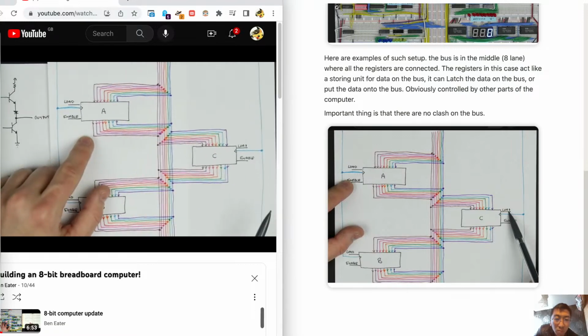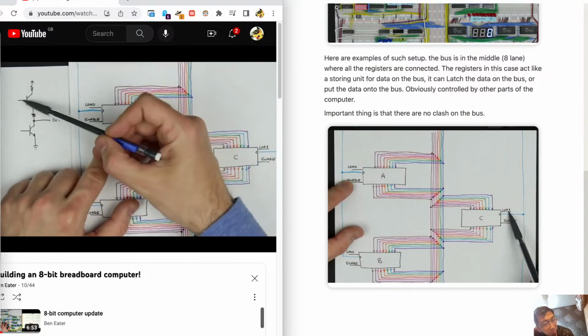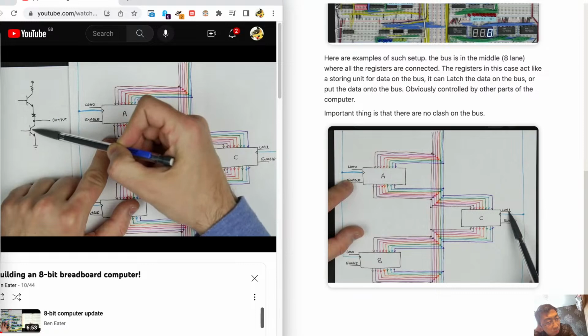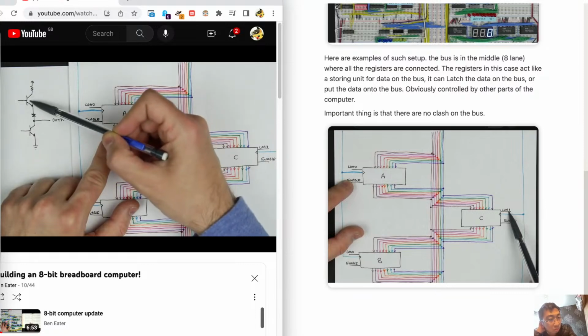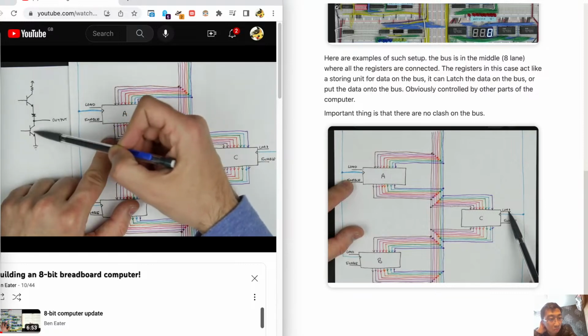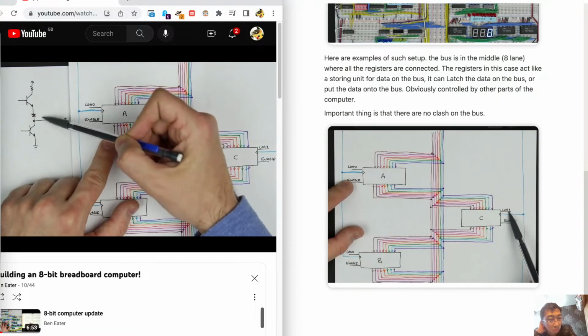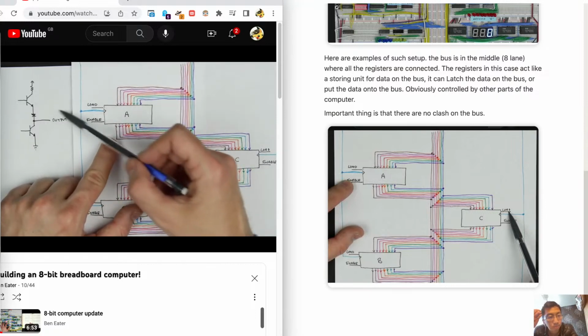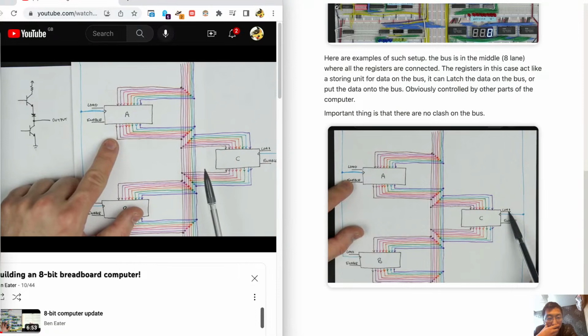And so there's a way to do that, where this gate, rather than turning on this transistor to output a 1 or this transistor to output a 0, if you don't turn on either transistor, then the output is not going to source current or sink current. And so essentially you're not going to get a 0 or a 1. You're just going to kind of have this output disconnected almost.